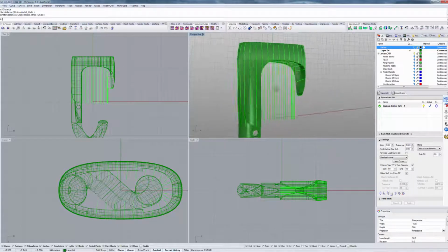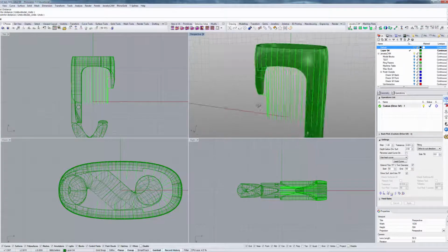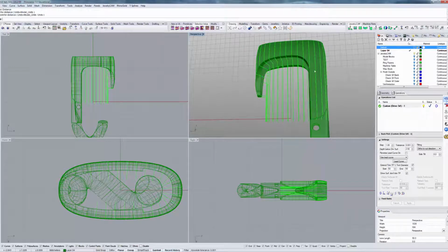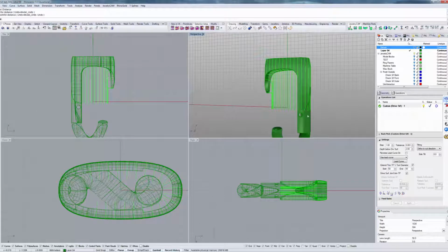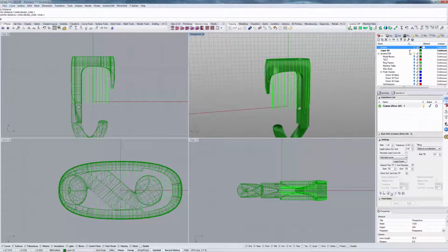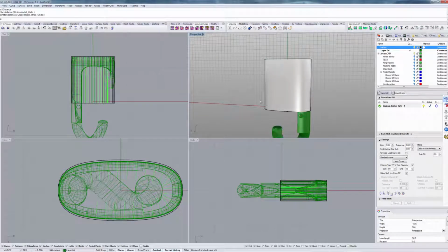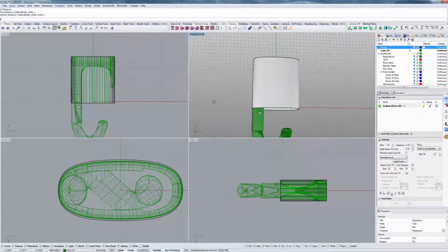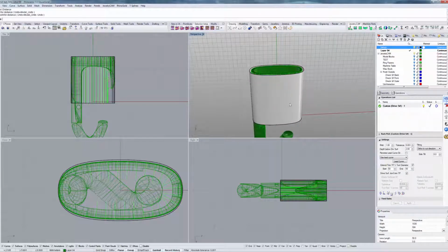In a sense, this is the essence of the drive surface operation. There's a few refinements that you could do, but this is the primary function of it. You create a drive surface, and that's what you end up spending some time thinking about and figuring out. And your drive surface almost invariably ends up looking like a ribbon, a piece of cloth that surrounds your model and moves along the track that you want your milling to take. It could be like this, it could be in a spiral. As long as it's a single surface, not a poly surface, it will work as a drive surface.